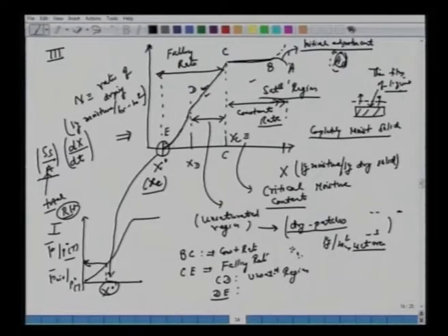Now here also is a falling rate, the second component, except this is a region where internal movement of moisture, or you can say pore diffusion and capillary effects, start taking place. That's why we have different characteristics from here to here and from here to here.